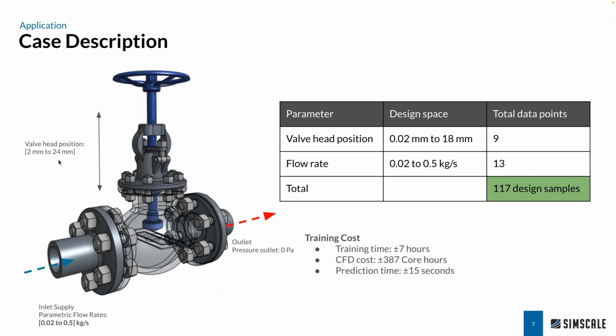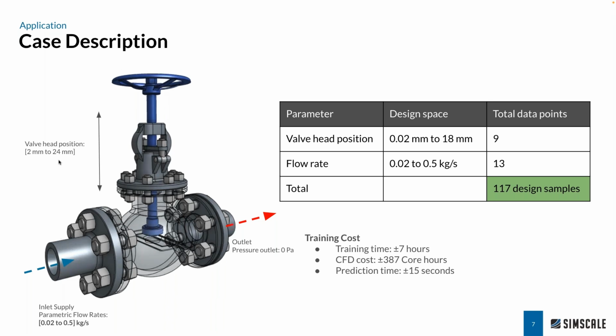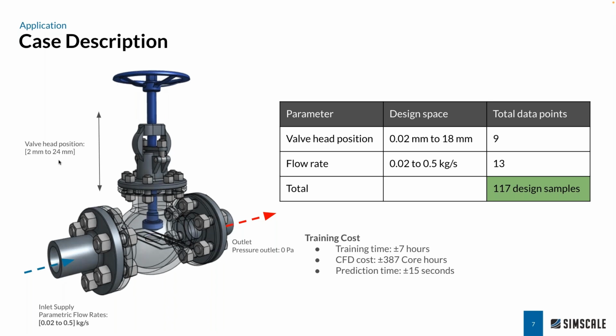This depends on the case; your case might be simpler or more complex than this. As a rule of thumb, I would say 7 to 8 simulations per geometrical variation will already give you a high level of confidence, about 90%, as we have seen in our cases.